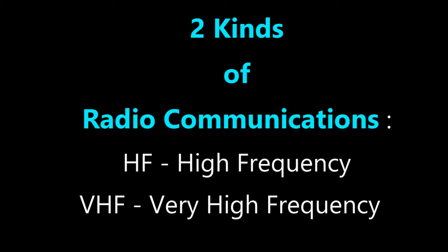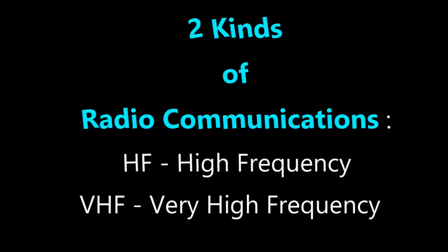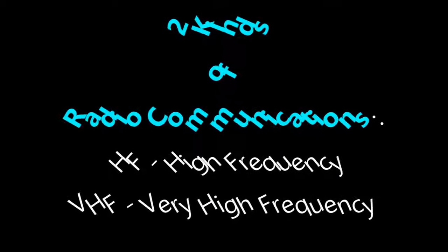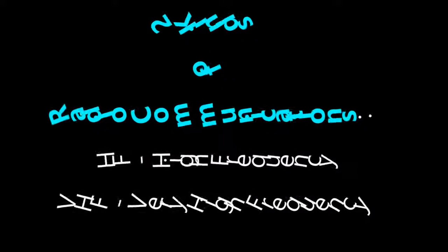Each of them has transceivers. We'll get into a little more detail further down, but there's an antenna, and one of them has a coupler, but you definitely have the transceivers in both situations. Your RMP, which is your radio management panel, is basically a centralized place for frequency control of the two frequency systems I just mentioned.